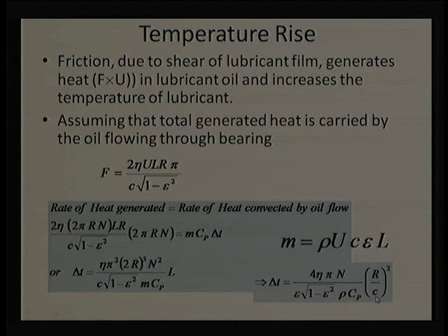After substitution and rearranging, what we get is a ratio r by c square, and this is related to the liquid specific heat and density, the speed and viscosity. So, larger viscosity, larger temperature rise; larger this ratio r by c, larger will be the temperature rise. Larger the density, which generally does not happen, this rho and Cp will remain constant, so it is not going to affect much. If I change the liquid lubricant, this product is not going to change, but because of viscosity it will change.